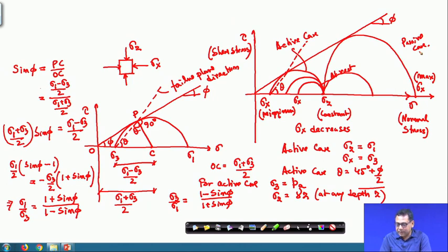Okay. So, remember that, because here also this Mohr circle touches the failure envelope line. So, you will not get a sigma x value more than this, but this is the maximum sigma x. And again, if I join these two points, and if this is also theta, so again this is the active passive case. So, in the passive case, this theta value will be 45 degree minus phi by 2.